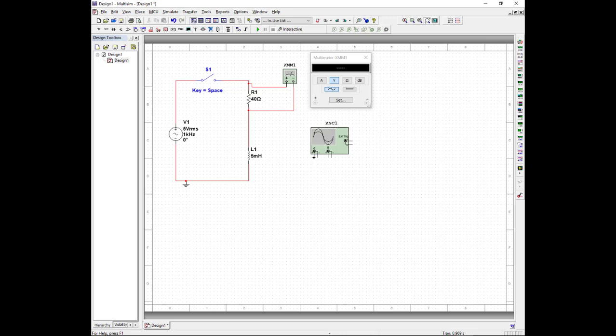So again, if I click on the probe, the channel there, I'm going to put it down here, and then I'll bring it up. Click here, just to give it some shape, and click into my circuit here, and then I can bring my 0 over here and tie it to ground here. We also have a trigger over here for if we wanted to connect up an external trigger. We won't be connecting up an external trigger for what we're going to be doing with it.